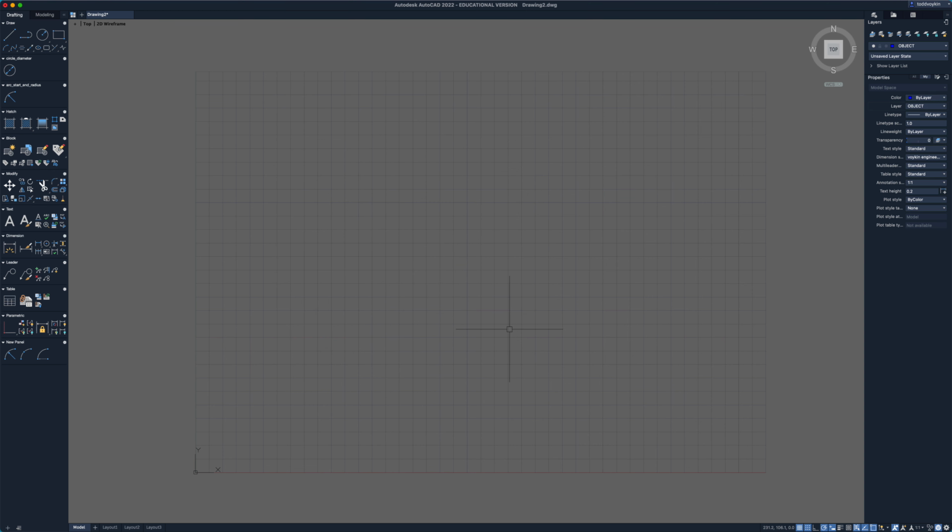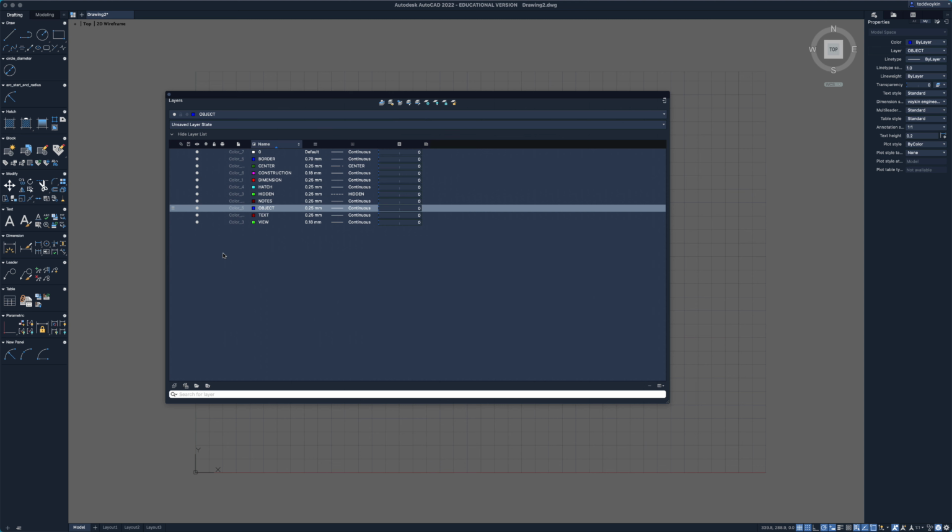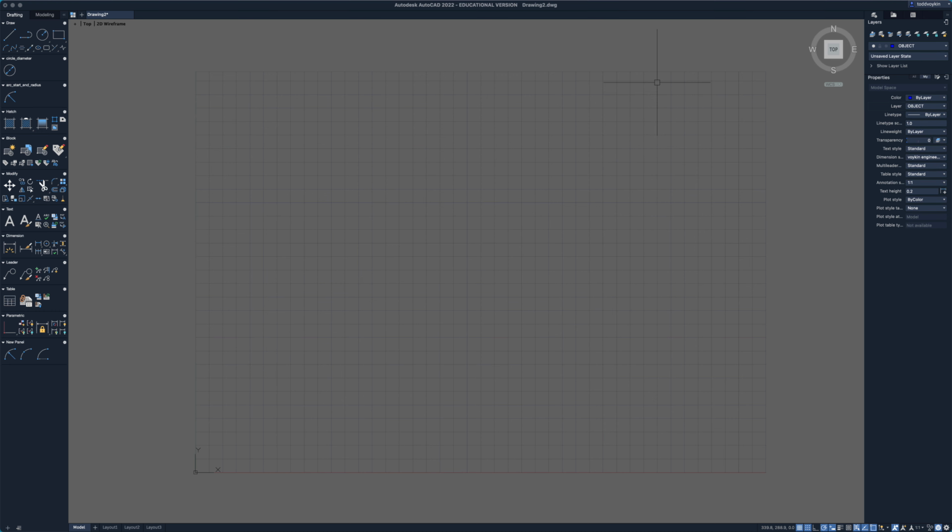We also want to do that with our layers and our text style. So let's go here to layers and bring that back in here. And now if I go to this far left column and I click, it makes those three little lines. That's telling me that that's the default layer. I want to choose object layer as my default layer. So that means when I open up a new template, it's going to be ready to draw on the object layer. It's going to have Voikin engineering drawing style set as its default.